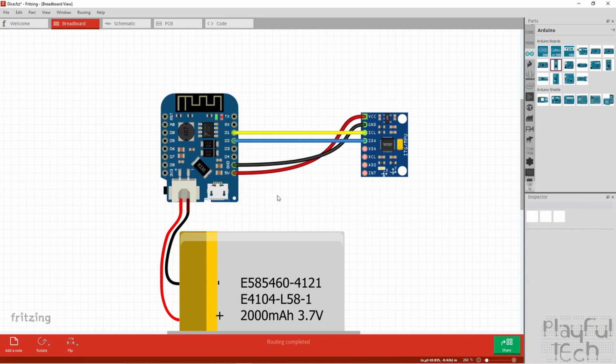Okay, now let's look at the interface between the Wemos and the sensor board itself. So the ESP chip on the Wemos runs at 3.3 volt logic. So when you write a high signal to any of the GPIO pins, they carry 3.3 volts. And the sensor board over here also runs at 3.3 volt logic, so this is perfect.